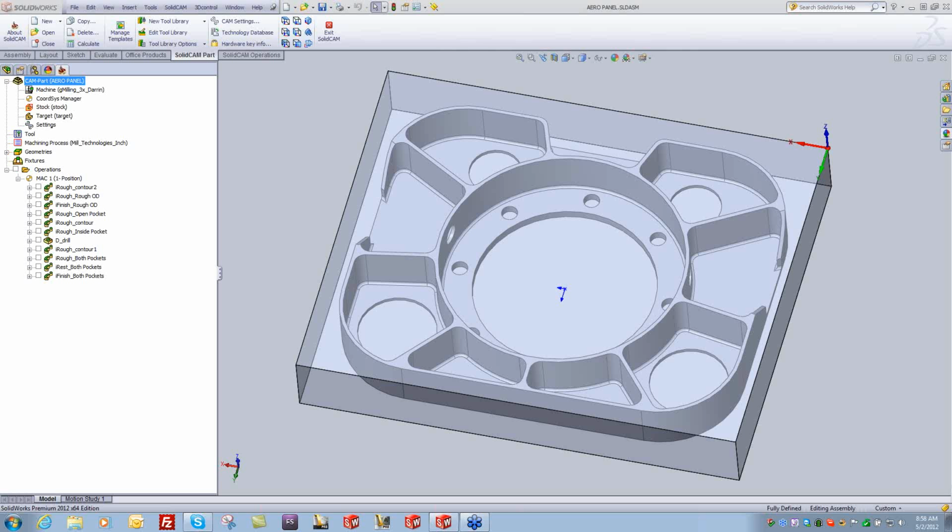And Greg, I will get with Chris and get back to you with an answer on that multiple finish pass cut. I might be missing something, or they just haven't put that in yet, but it would be a nice addition. I agree that a spring pass is not a bad idea. Because we're managing the tool engagement, you're never taking too much material, so you should be pretty good after that finish. However, I've always gotten used to taking one or two spring passes, especially if I'm looking for a very accurate size on a wall. So I agree with you.